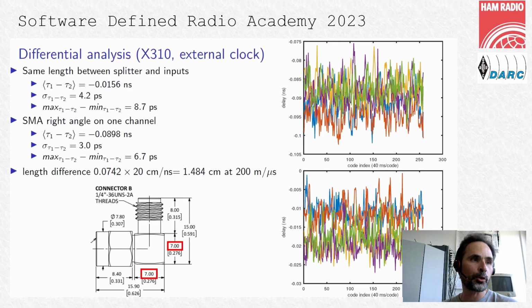And if you look at the geometry of an SMA connector as the one we use, well, you've got two lengths of about 7 millimeters, which add up as something like 14 millimeters. So I think we can reasonably claim that we do measure with sub 10 picosecond time delays between our measurements. This is all done by referencing every clock on an ultra-stable clock source, a hydrogen maser. So the FPGA, the software-defined radio, everything is clocked on a hydrogen maser.